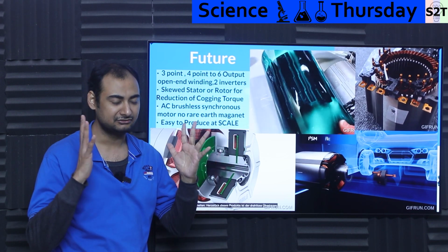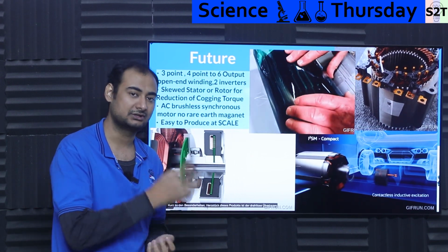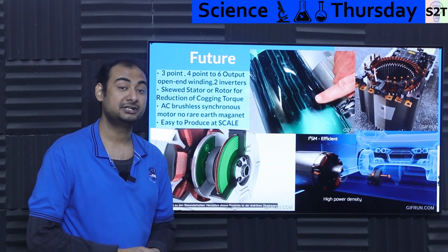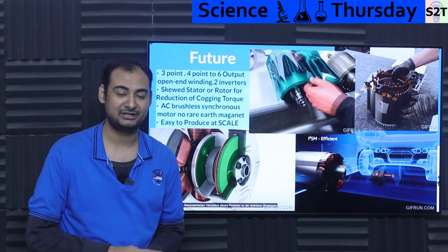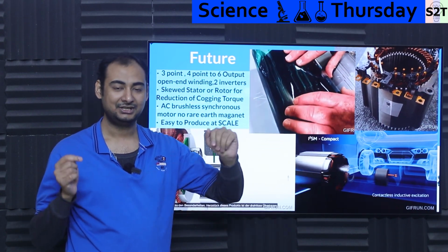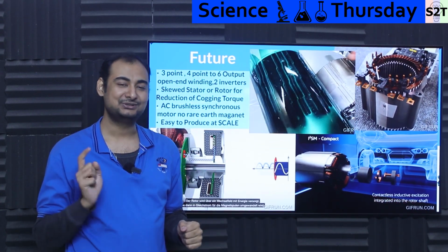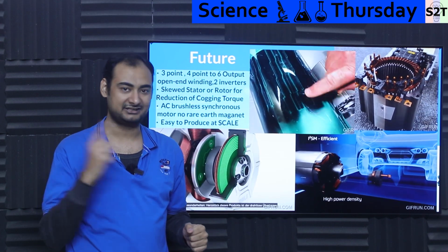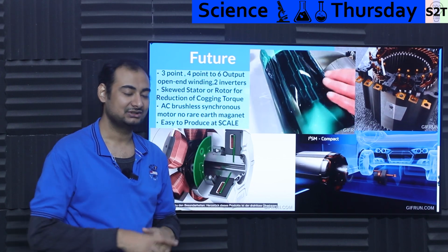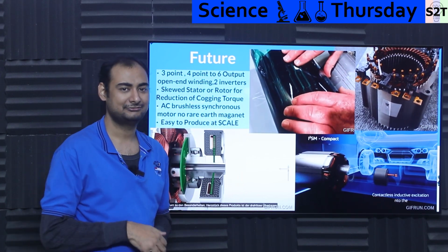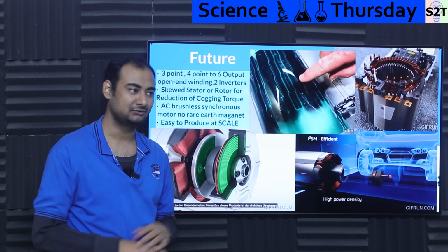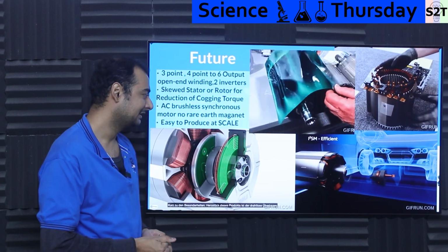Benefit of that, you can precisely control how much oomph the rotor has. And again, at high speed, you want that to be low. At idling mode, you want it to be off. Induction motor does have that benefit. Basically, if you have two induction motors, front wheel and rear wheel, both have induction motor, you can turn one of them off. You can't do that if you have magnets. Magnet will always create a drag, magnetic drag like of eddy currents, even if the motors are floating. So it will cause an issue. Here it's like, bro, turn it off. Turn it off means turn it off. It's off. It's done. You will only have bearing drag. So that's a good thing.